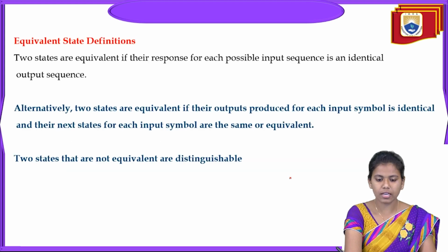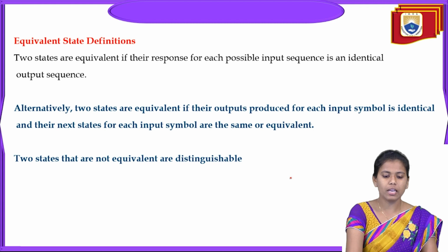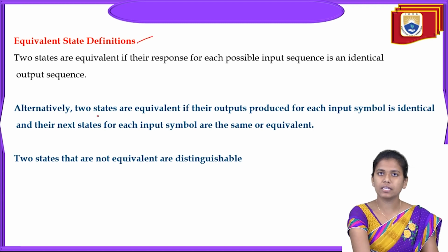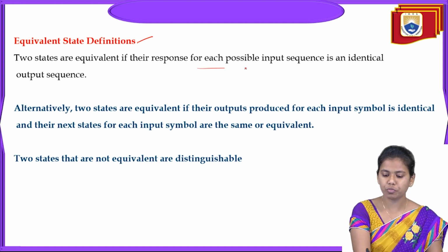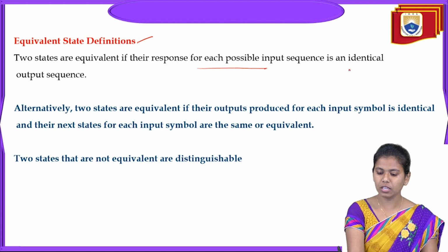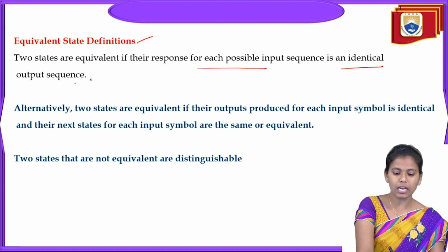So this is just an analysis example based on the flip-flop. And now we will see the equivalent state definitions. So what is this equivalent state definition? Two states are equivalent if their response for each possible input sequence is an identical output sequence.